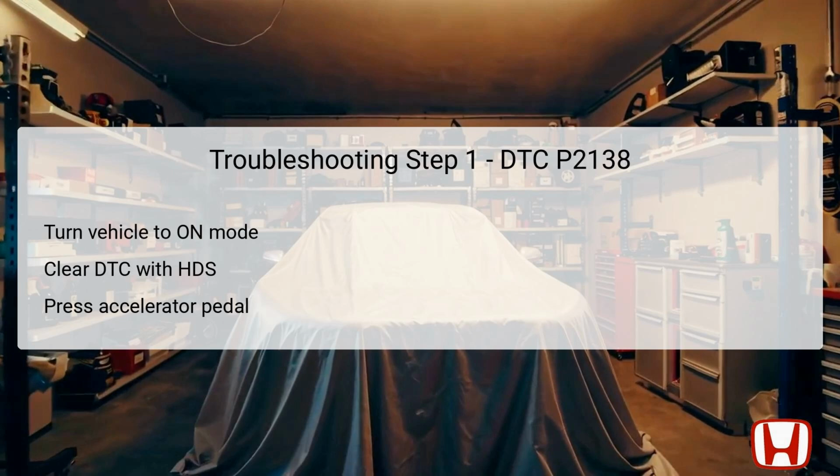reassess whether the P2138 DTC is still indicated as either pending or confirmed. If the DTC reappears, further diagnostic steps are required to isolate the problem. However, if the DTC does not appear, it may imply an intermittent issue or temporary fault that warrants further inspection of the relevant connections and terminals.